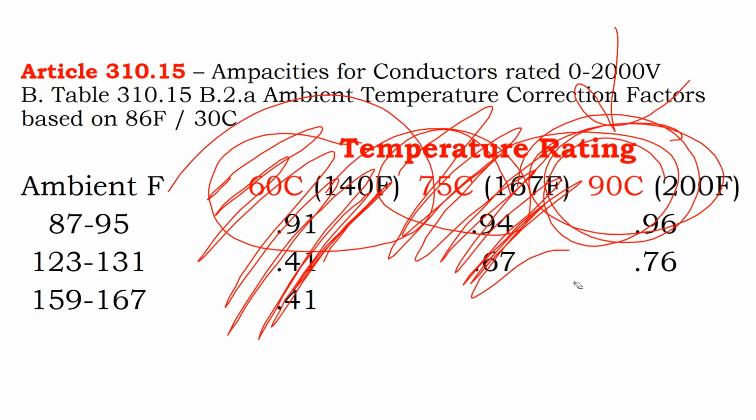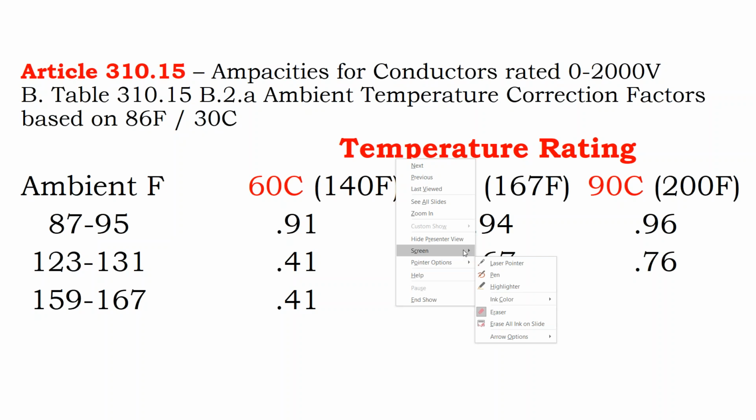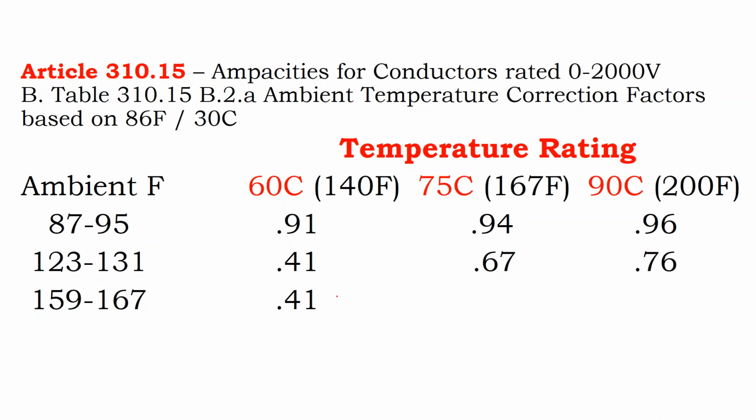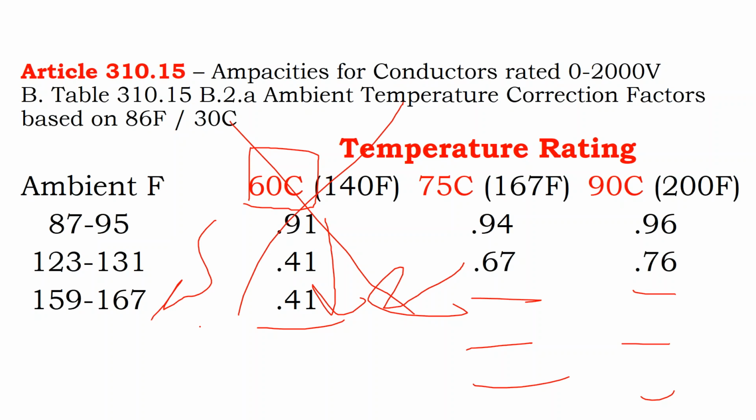And then you look at all these tables, table upon table upon table in the National Electrical Code. And then, well, where's all this data coming from? Well, we see that if you're using a 60 C wire and you get into elevated temperatures, eventually the derate trend, this table will end, and these will keep going until they approach close to 40%. But eventually your 60 C wire cancels out, you know, pretty shortly after it exceeds its temperature rating.